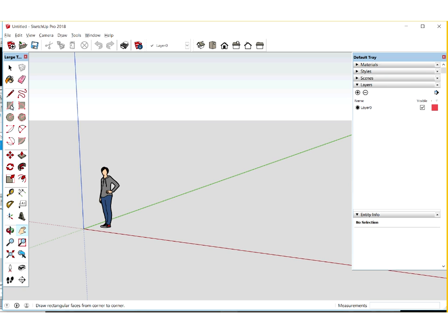So with your rectangle tool, if you click on that, start at the origin. The junction between the axes is a really good way to just start a project, because you know that that's at the 0 level in terms of height. So I'm going to click and release the mouse button, drag away in the direction that I want. I always exaggerate the size or the proportion of the shape that I'm creating there, so I can see in the bottom right of my screen, if you have a look down the bottom right corner, which is going to need to be the long and the shorter of the two dimensions I'm going to type in. So I might make this 8 by 4 meters, for instance, today.